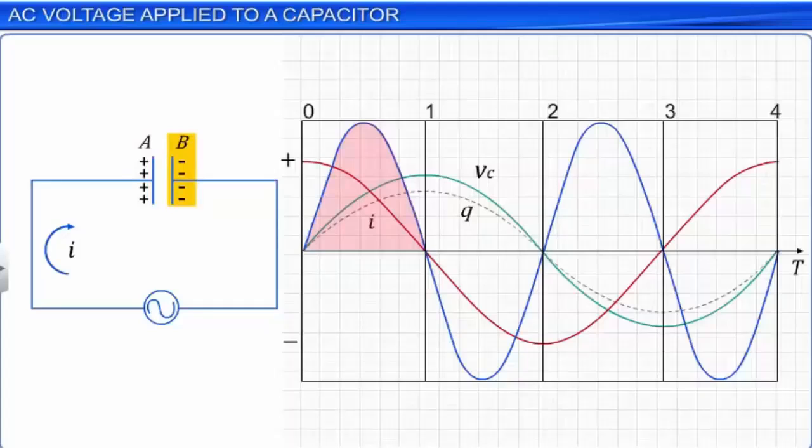The plates are fully charged at the instance 1. The voltage across the plates is in phase with the charge Q and peaks at time t equal to 1. As the current and voltage are both positive, it means that the power is positive. Positive power refers to charging of the capacitor. Hence, power is being absorbed by the capacitor and it gets charged.